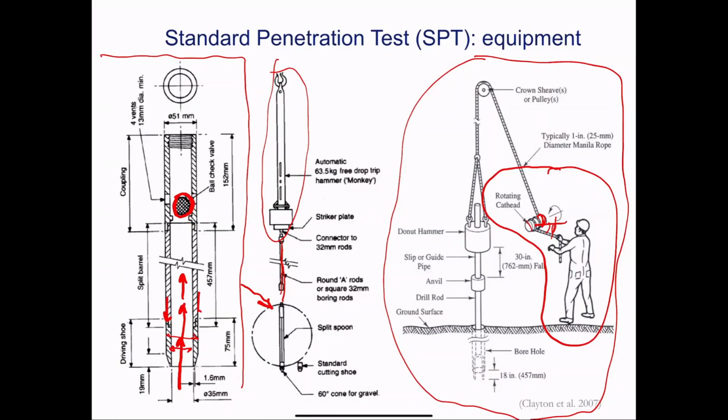I think most of you are doing a capstone project where you look at GI logs, right, for the geotechnical team members, and you see N values, right? Often these are not N values. You see them called N60 values. Some of these are even called N160 values. The 1 is mostly for seismic related topics, but you might even see N160 as well. Just different names for what we treat as a standardized N.